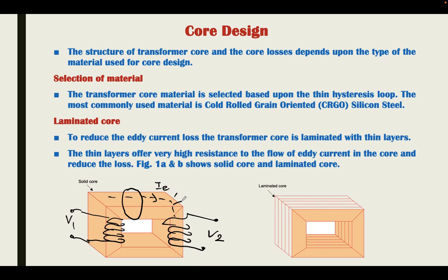Because this core has internal resistance R, there will be I squared R loss, and these losses will heat up the transformer core. The loss due to eddy current is known as eddy current loss, and it may cause extra heat in the transformer.